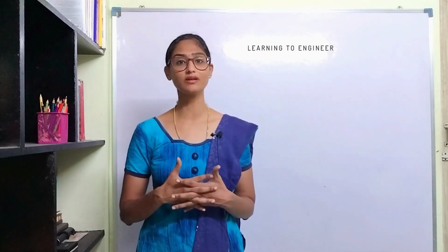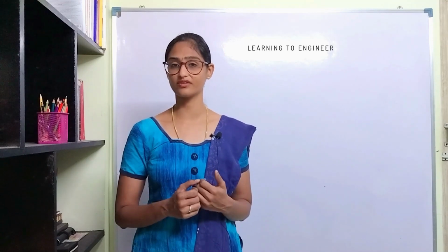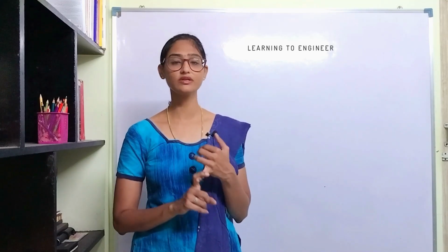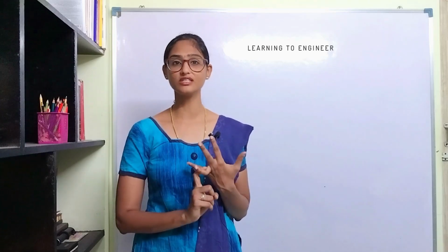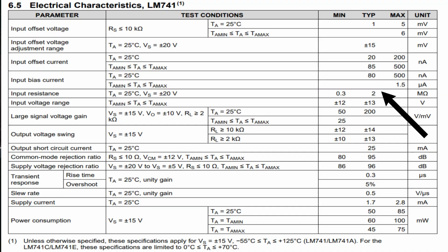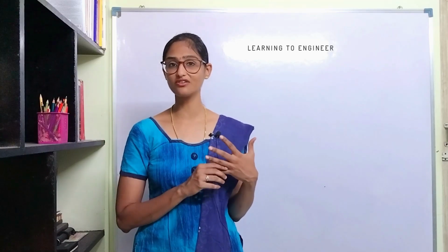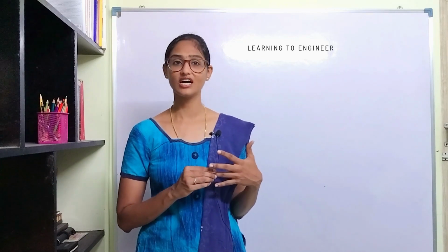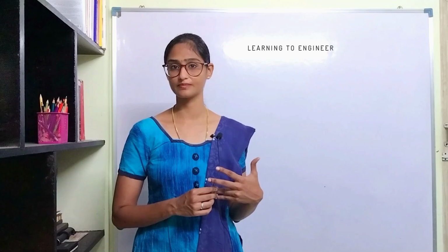We can simply replace it by a wire, provided it provides these two facilities: the gain should be unity in all cases, and the input impedance should be very high, because it isolates this amplifier from the input circuitry. To provide this kind of isolation, we need a device with a very high input impedance, and that is why we are using an op-amp.